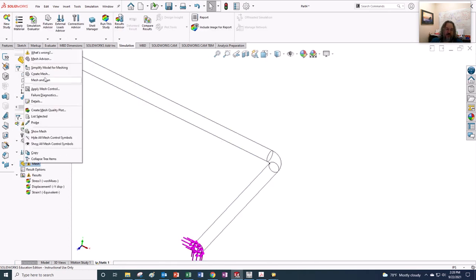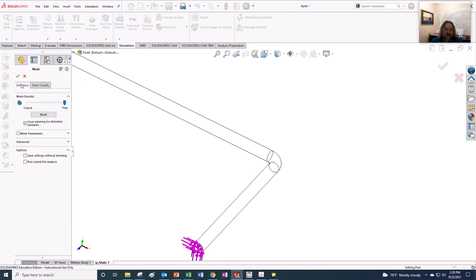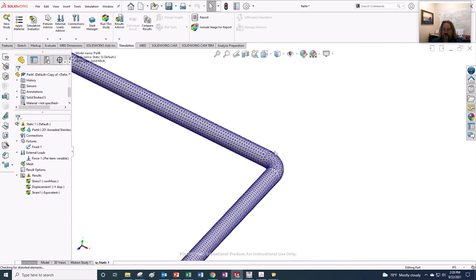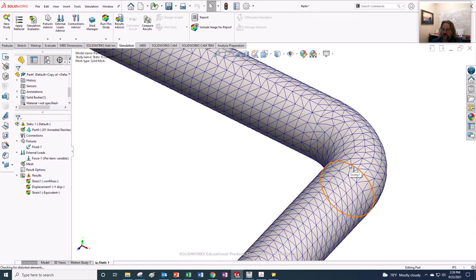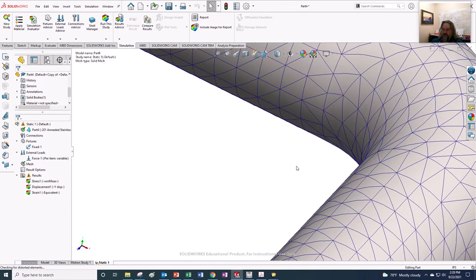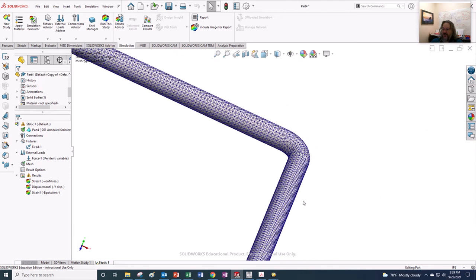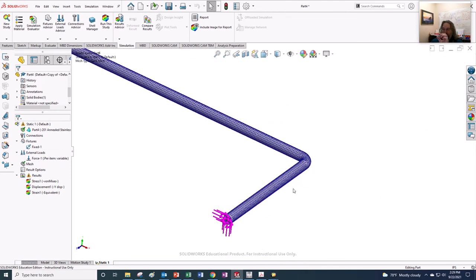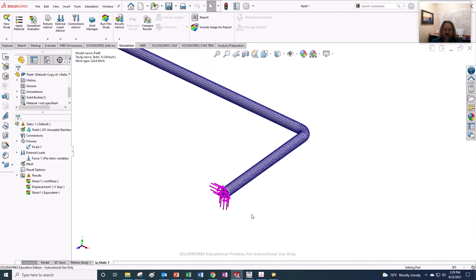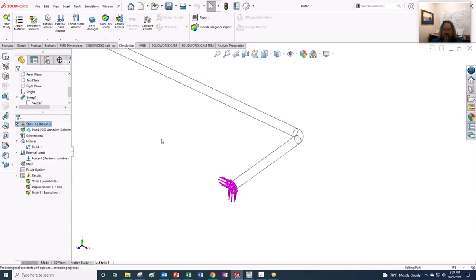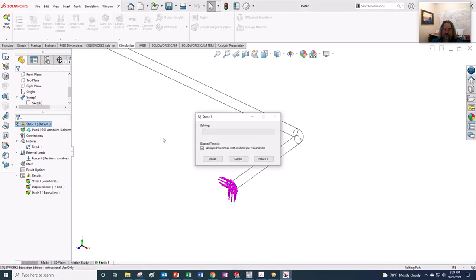But if you didn't know that from experience, you might get frustrated by this, but it should mesh now. Yeah, see, it meshed. And you can see that right along there, there's a node right along that curve, and there's a node right along that curve. The thing is that they couldn't figure out how to mesh, because we had that one little hard point that it went down to. We got mad. So let's see if this has any amount of influence, and